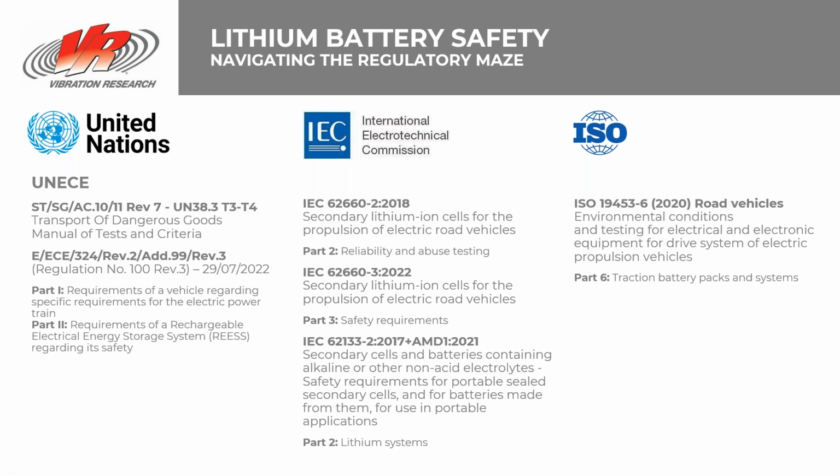That is for regulatory approval of transportation of lithium-ion batteries, so you should be doing that test on the actual transportation packages. But I've seen it being bandied around as a possible test to be applied to a battery pack itself. But I'd always be looking for that to be done in whichever way the battery pack is going to be transported.